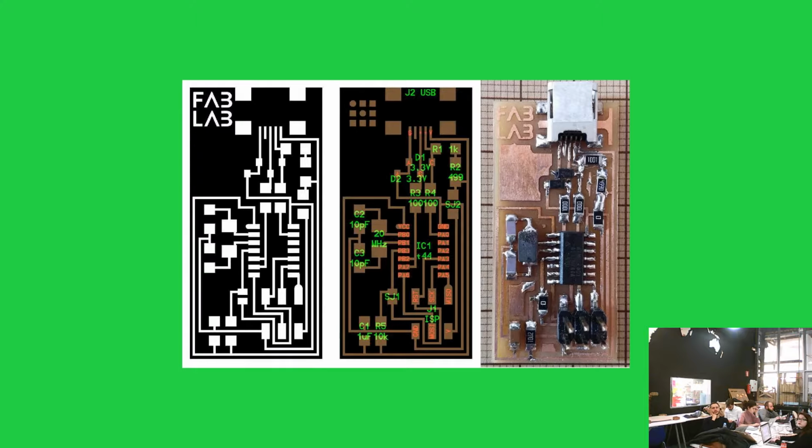What you want it to do is, from USB, create a protocol called in-circuit serial programmer to program your chip. That's a code that's the same for all of you, so you don't want to customize it. Someone at Fab Academy already created it, so you would just need to download the code and put it inside, right? And the power of this is that this microcontroller, as you say, is a general purpose computer, as we discovered before.